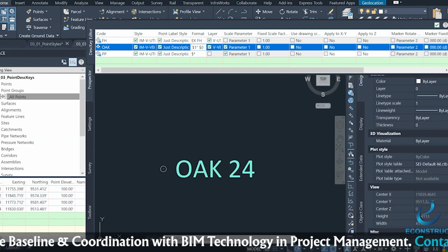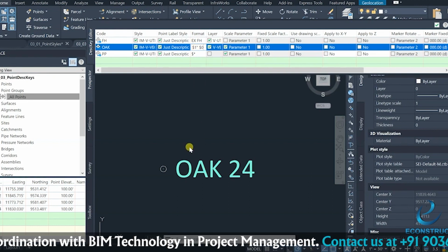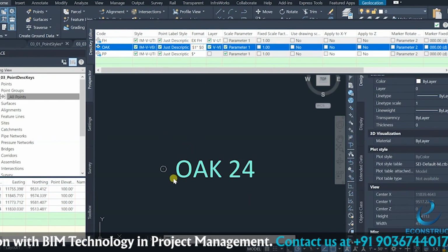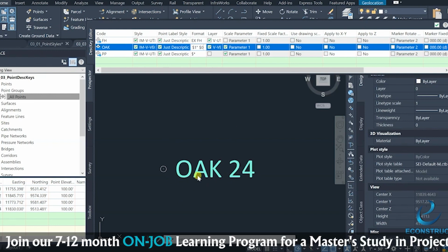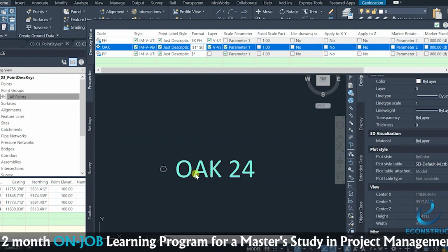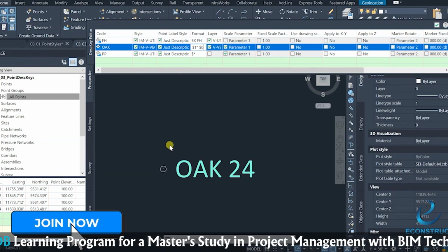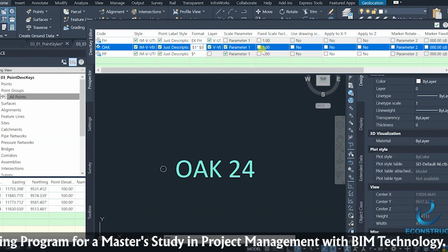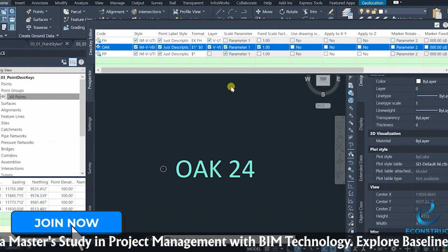Since I have replaced $0 with $1, when I refresh this description key set, it will be shown as 24-inch. Yeah, 24-inch, and oak will come after 24, and the scale will also be increased because I just changed this scale. I'll set it to 1 so that the scale factor will change to 1.